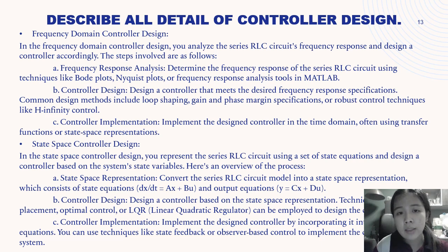And about frequency domain controller design, you analyze the series RLC circuit response and design the controller. The frequency response analysis is to determine the frequency response of the series RLC circuit using techniques like Bode plot, Nyquist plot, or frequency response analysis through MATLAB, and then the controller design.